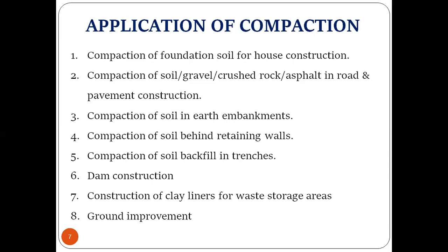And next is compaction of soil in earth embankment. If you are going to provide any embankment, then to properly provide a stronger embankment, we have to compact the soil, right? On that embankment, whatever soil is there, we have to compact or pack it properly, so that there should be no failure of the embankment.